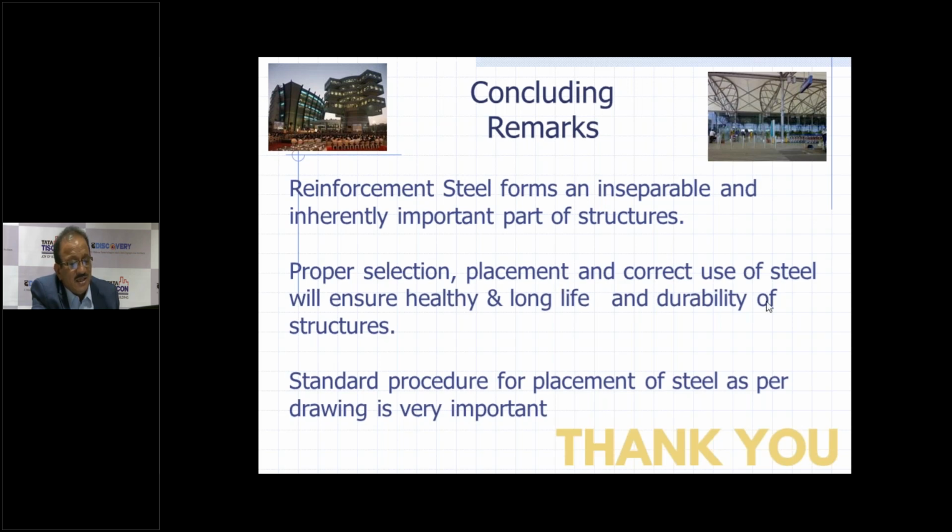You have to see that these steel pipelines should follow the criteria for providing the cover. You cannot allow it to touch the steel shuttering. It also should have the proper cover like steel bars. That is my practical solution for that.